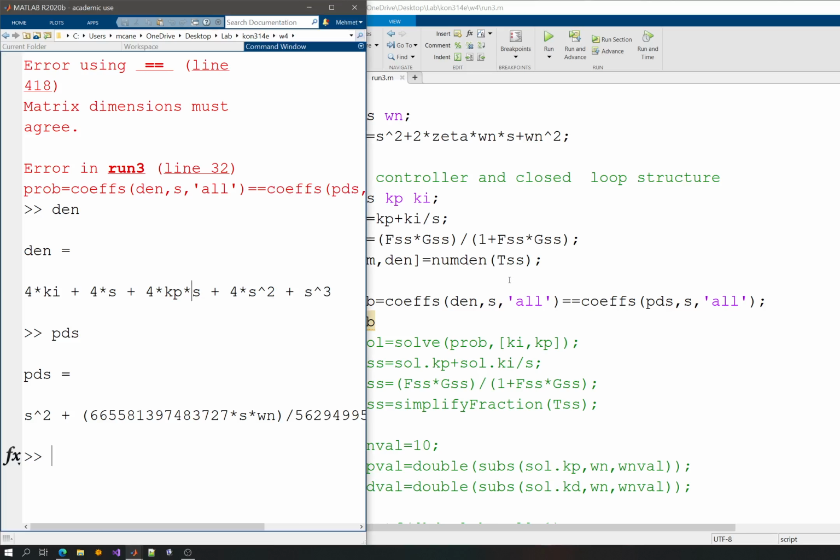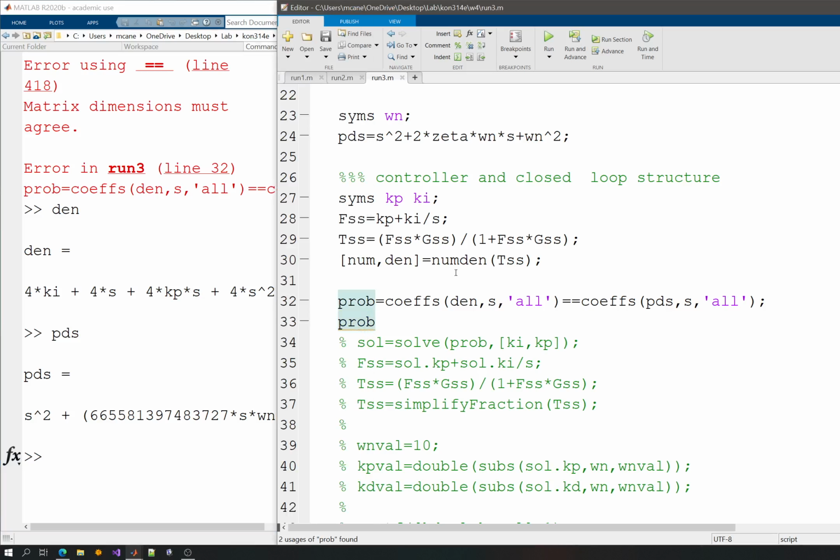In this case, if you remember, we were using the dominant pole placement approach, which means that if we have higher order systems, an order higher than 2, then we are not able to calculate the settling time, overshoot values, etc. But what we can do is choose a pole pair which represents a second order system, or the second order part of the system.